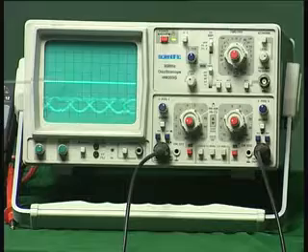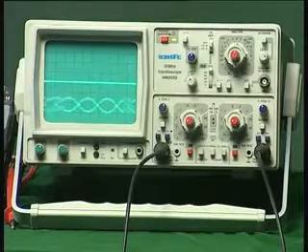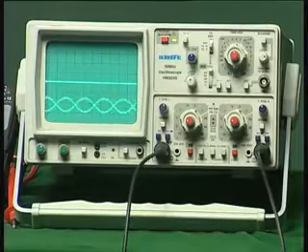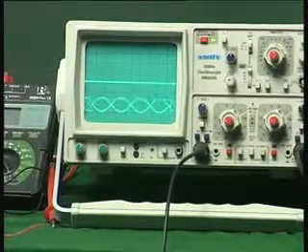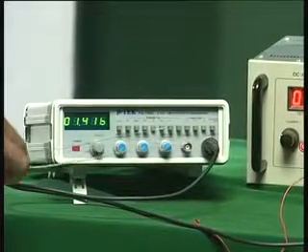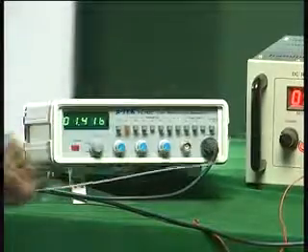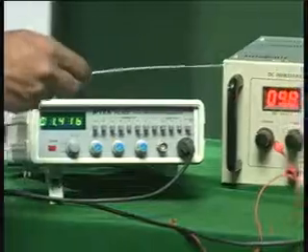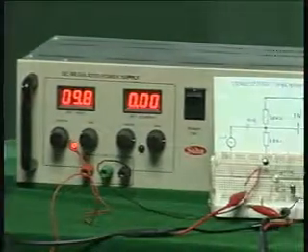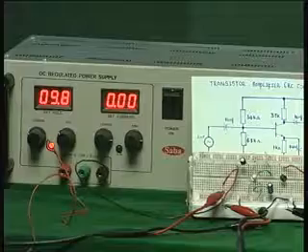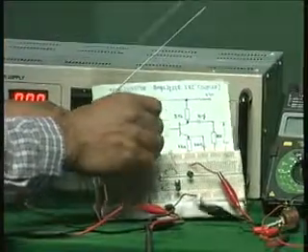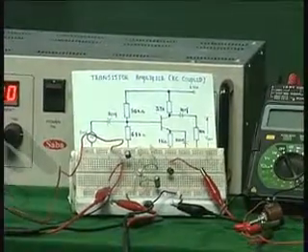Right now I have not switched on, so you are not able to see the signal. So this is the oscilloscope which I can use to find the output signal and the input signal simultaneously. This is a function generator which I am using as a signal source and applying the signal to the input of the amplifier. This is a power supply which I am using for the VCC supply that I require for my transistor amplifier. Now let me quickly apply the AC volts at the input,